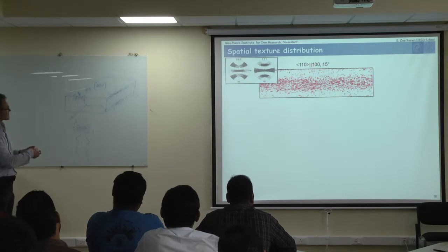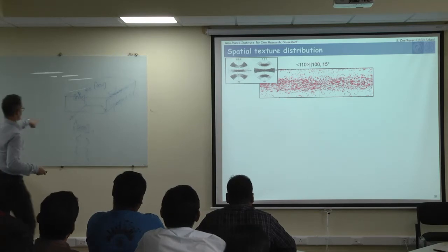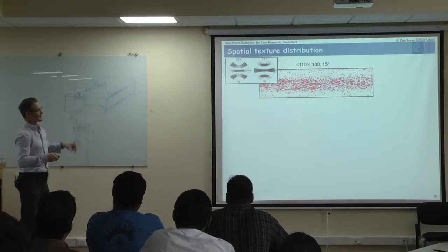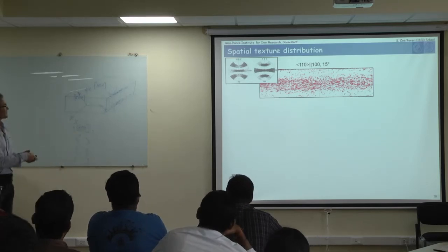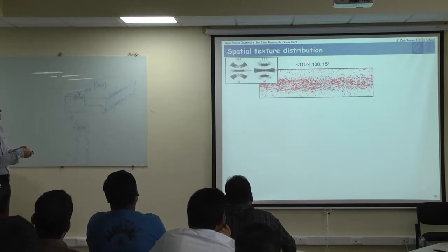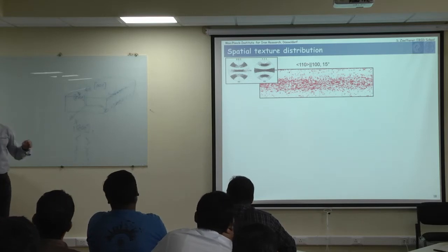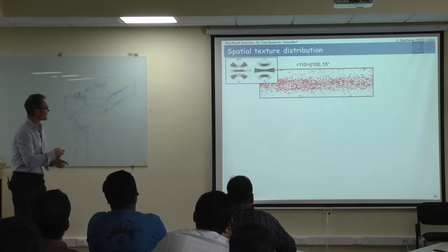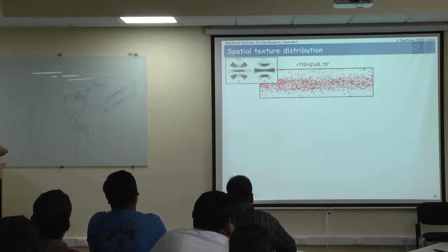And actually, here I selected the following writing. Instead of using these square brackets, I don't use any brackets. I write the crystallographic directions with the conventions. So sharp brackets mean all <110> directions, and square brackets mean only one particular [110] direction. And the sample direction I indicate without brackets. So if I plot here for the center of this area, I plot how many crystal directions of 110 type